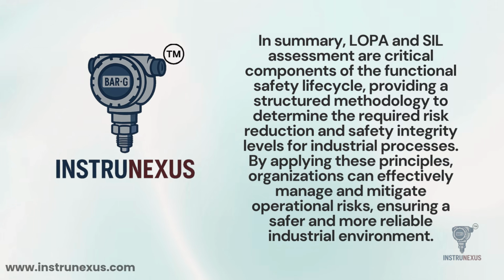In summary, LOPA and SIL assessments are the backbone of modern process safety. They provide a structured, defensible, and mathematical approach to deciding how much safety is enough. By rigorously identifying initiating events, validating independent protection layers, and calculating the risk gap, organizations can effectively mitigate operational hazards. This makes our industrial environments not just more compliant with standards like IEC 61511, but genuinely safer for the people who work there every day.